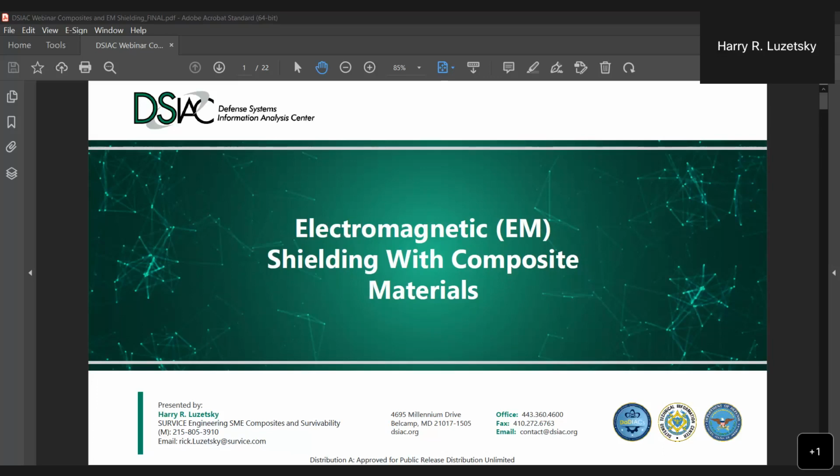Well, we actually have a couple of things. It's an expanded copper mesh that we have in there, and with the expanded copper mesh, we want to maintain the structural properties. Even though, from some testing that I've done in the past where I've put an individual layer of copper in there, we know that if you do that, you're going to have a bigger effect on the structural properties, for one thing. The other aspect is we're also looking at the copper mesh as a way of filtering out some of the radiation, actually taking advantage of the mesh itself. There is data that shows that different mesh configurations or sizes can actually have an effect on that radiation and can give you some benefit to the shielding effectiveness.